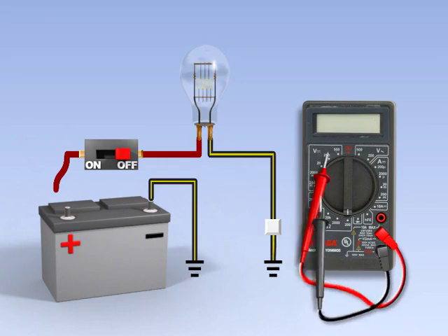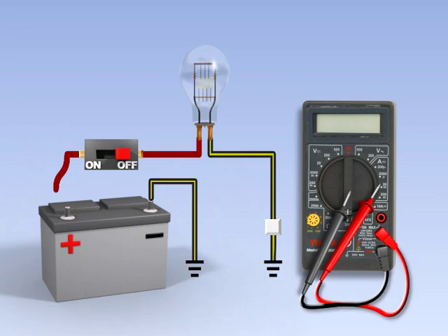To find the problem, trace the circuit from the component to the ground source, checking for continuity between connections. Repair or replace any faulty wiring.